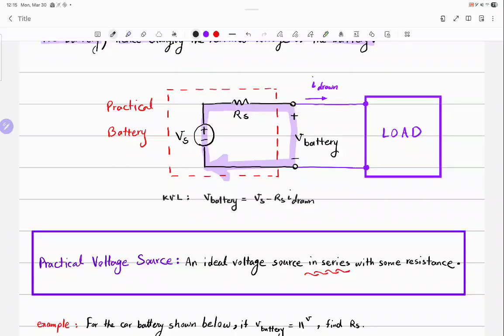Have you had Physics 202? Okay, is it about magnetism? Are you familiar with Faraday's law? Or in high school or somewhere? If you change the magnetic flux passing through a loop, it will create some electromotive force, right? And that loop doesn't have to be closed. You still create that electromotive force. What happens if the loop is closed? Then you will have current, okay? So current needs a loop to be closed, but voltage, no.